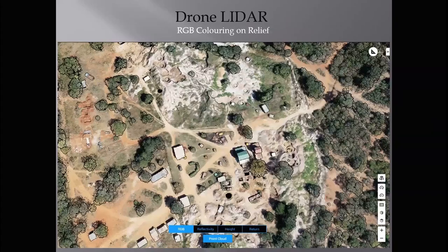What about the cameras, the LiDAR, the altimeters, the hyperspectral, all of that? Okay, here's an example of what we do with LiDAR on a drone. LiDAR are usually quite expensive. If you do it with an aircraft, much cheaper with a drone. What we can do is we now measure with the laser. LiDAR is laser interferometry, basically. This laser fires, again, something like 20,000 times a second, and it picks up every little blip in the terrain.